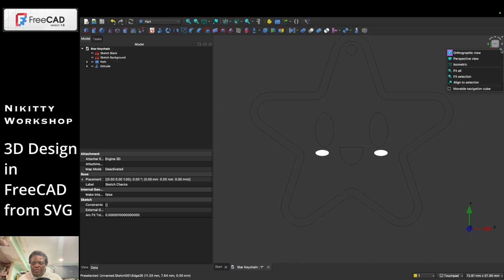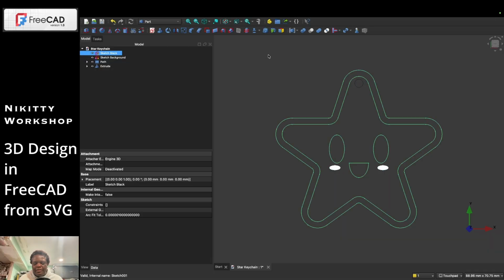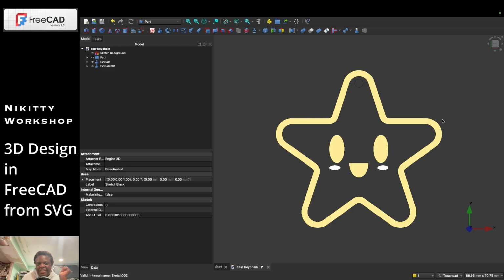And then if you hit the little box and do fit all, you can zoom it in like that. All right, so now we're going to extrude the outline on the backs. So you select that and you're going to do extrude. So what should happen here, everything that's in the green should be extruded if I did this right. All right, so we're going to do 2 millimeters. This is plus, we're going to click OK. So it did do it. So we grouped these all together. Remember, we selected all of them together. So that's how we wanted to extrude it together.